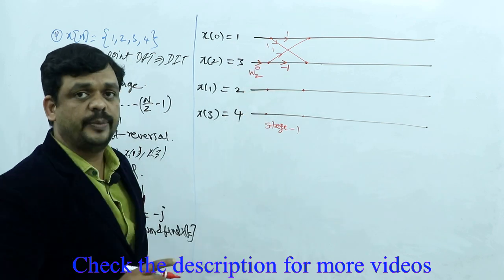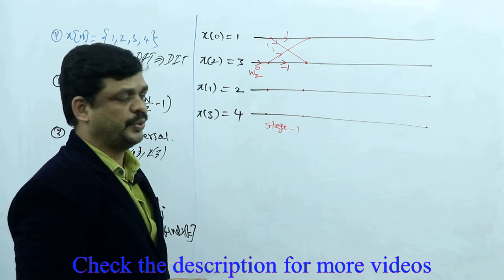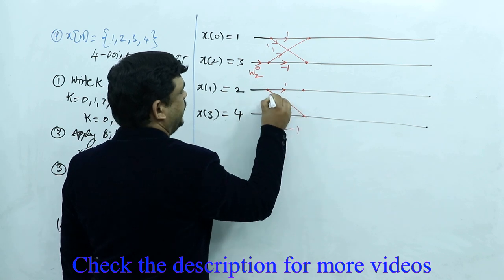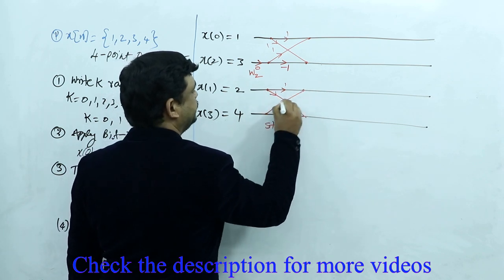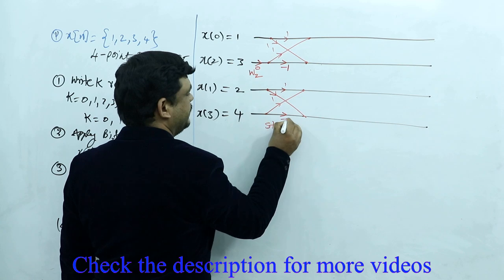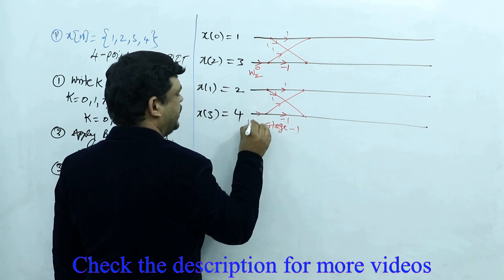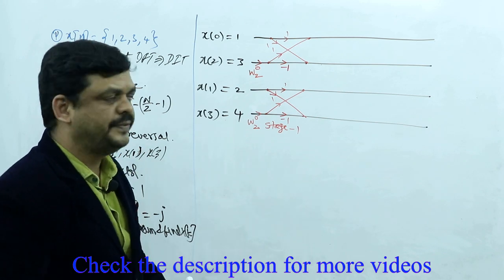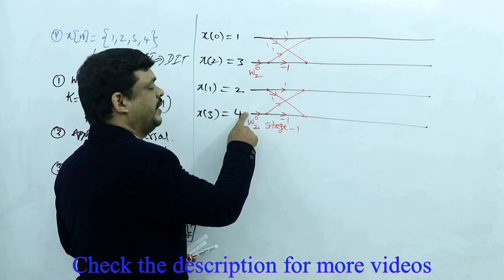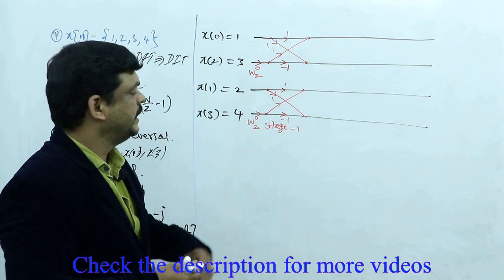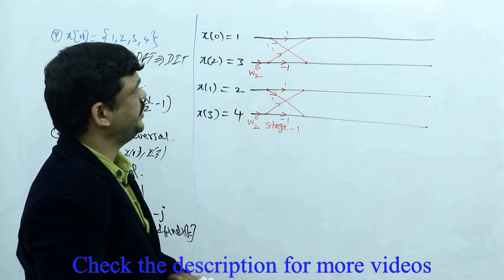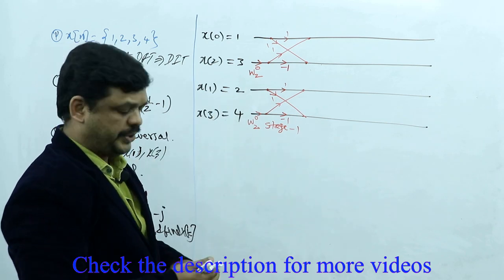The trivial factor is W2 power 0, right? Similarly in this case also the same thing. Here draw one more butterfly diagram, and this explains the -1, and here the trivial factor multiplies. Only one odd function is there, that's why only one trivial factor is enough. And here only one even and one odd, so totally 2 samples are there. That's why you have to take W2 power 0 here. So this is finished. Then perform the operation.